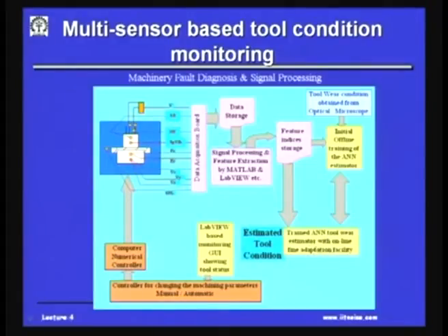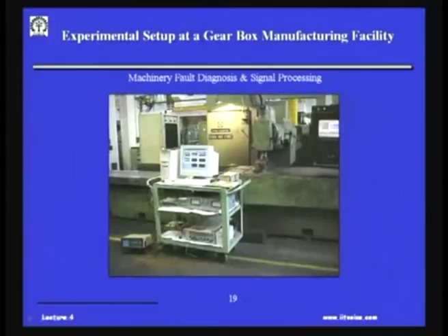And then try to find out at what tool wear, and what the remaining useful life of the tool is, wherein we say a tool fails at about 500 microns, etc. So how much time it would take for the tool to fail. This analysis was done with all the sensors taken together in the artificial neural network, because it would be humanly or physically impossible to have a mathematical model based system wherein all these parameters are taken in and compared to the tool wear. Rather, we thought of using an artificial neural network, which is very powerful in the sense that it's a black box which relates pretty well the output condition to the input level of the system.